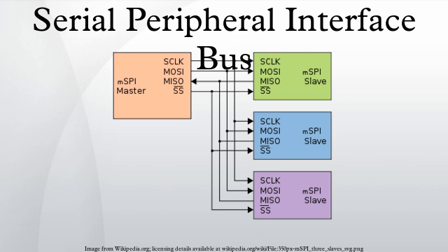Many SPI chips only support messages that are multiples of 8 bits. Such chips cannot interoperate with the JTAG or SGPIO protocols, or any other protocol that requires messages that are not multiples of 8 bits. There are also hardware-level differences. Some chips combine MOSI and MISO into a single data line. This is sometimes called 3-wire signaling.